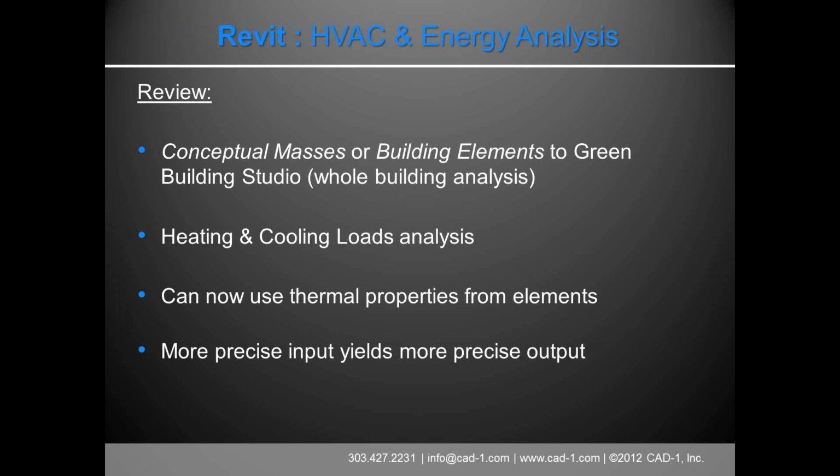Sorry. No, but the earlier you do it, the more latitude you have to make broader changes that affect the energy analysis, the water usage, et cetera, throughout the project. The further down the line and the tighter the materials, the glazing, and so forth get, the less latitude you have to really make changes that strongly affect the analysis. Maybe you can change the glazing type, but you can't do a whole lot else at that point. So you kind of want to run this through the progress of the whole project.